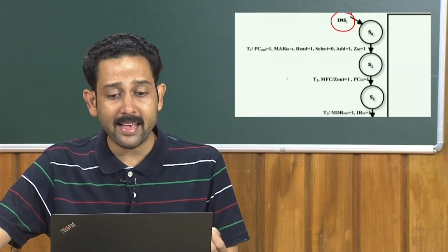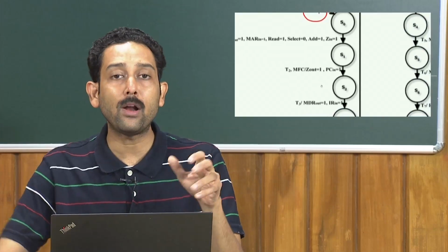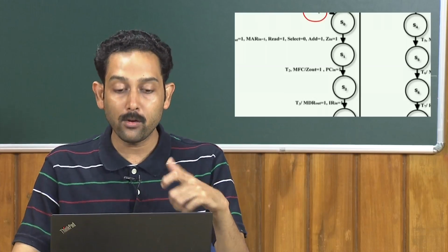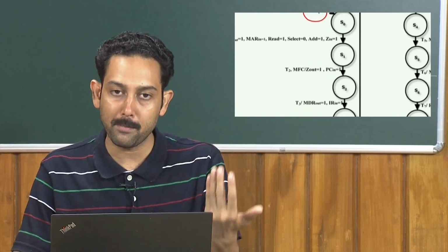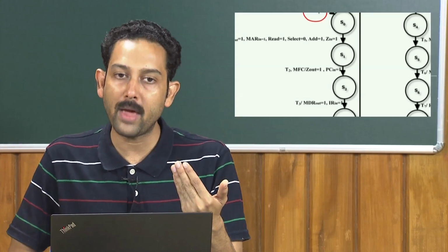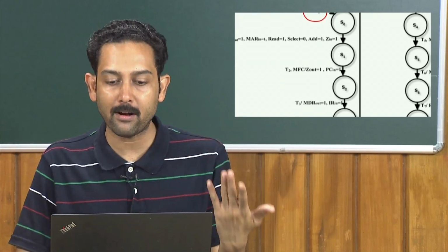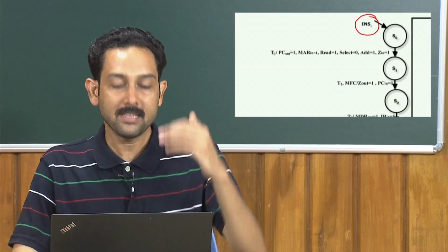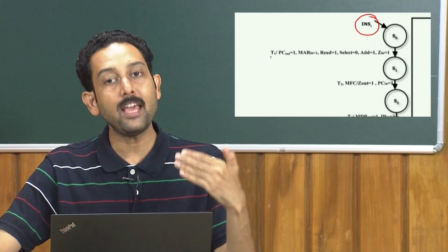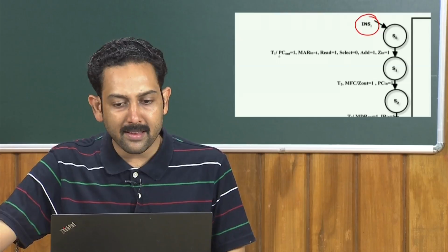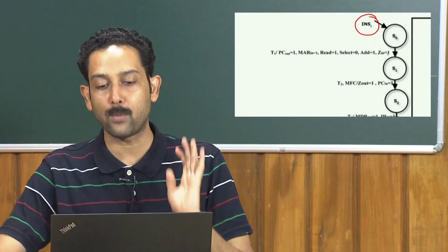Now for all cases, generally if you do not want to wait for any kind of external input like your condition flags or your memory values, the output of the memory, that is memory is ready, or some signals like you want to wait that if the flag is 0 or flag is 1. So if no such conditions are there, you just need to wait for the time, stage 1, stage 2, stage 3, these are generated by the clock and the FSM counter. Go to stage 1 and generate all the corresponding signals which are required.